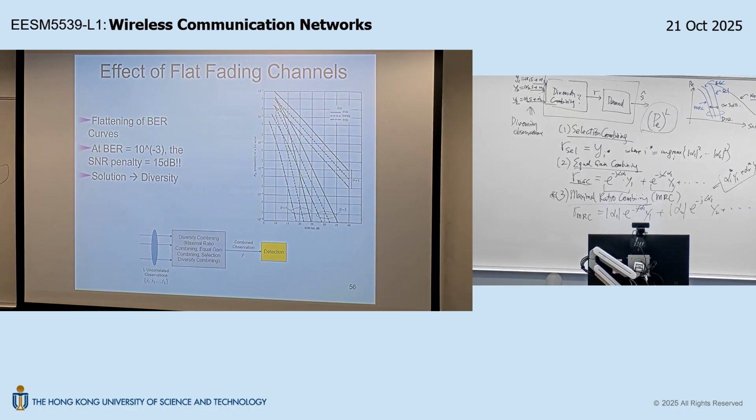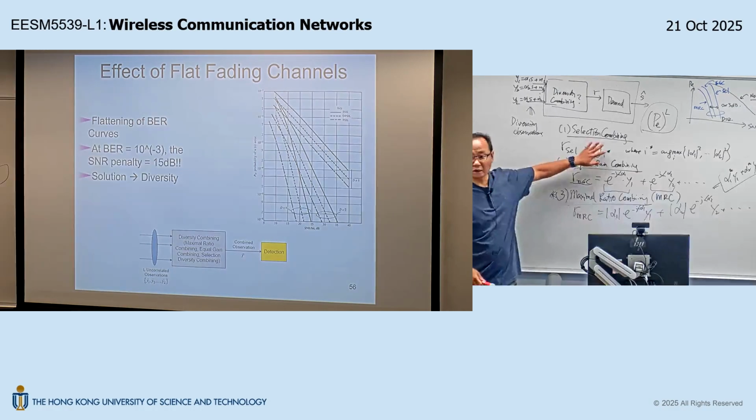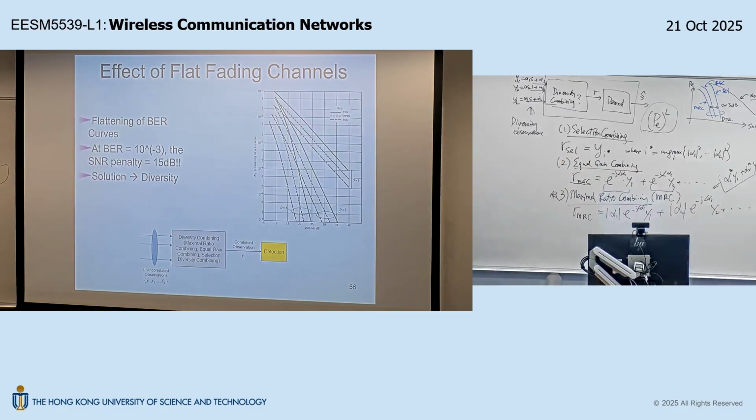Now, if you're doing the selection of the switch based on some random alpha, then you are not enjoying the benefit of diversity anymore because you are essentially doing random selection. You understand my point? The basis for this diversity benefit is that you are doing a selection based on a reliable channel estimation. And therefore, reliable channel estimation requires some kind of averaging.